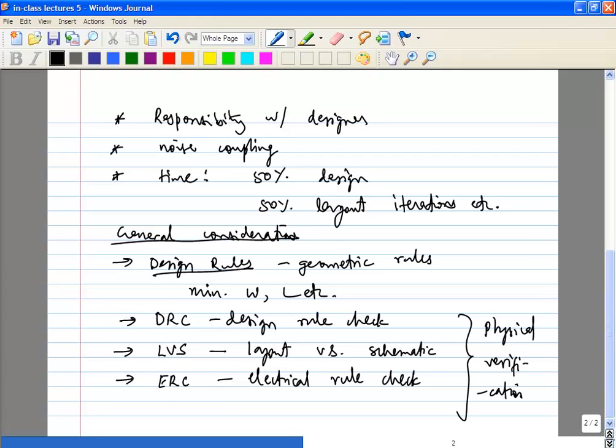Similarly, if you connect a thick oxide transistor or the IO transistor to a low power supply, what happens? You may design it for a certain resistance or a certain GM, and your VGS is going to be different from what you wanted to apply. So a transistor may have a lower GM. If you're using it as a switch, it may not turn on enough.